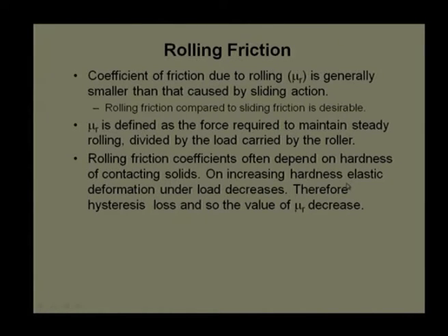And the reason behind this is that if there is a high hardness, the magnitude of deformation will be lesser, and the depth of penetration will be lesser in that case. So, if the depth of penetration is lesser, there is a chance that the material will show lesser hysteresis. If I think from the hysteresis loop point of view, from the loading and unloading point of view, if a material has a hysteresis behavior, it does not regain its position without losing energy, then the coefficient of friction will be high. However, if it regains the same position without losing much energy, then the coefficient of friction will be lesser.